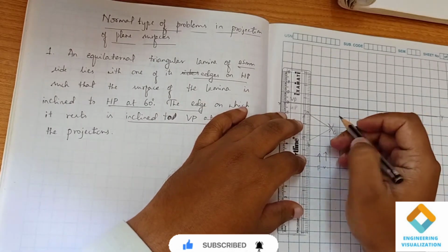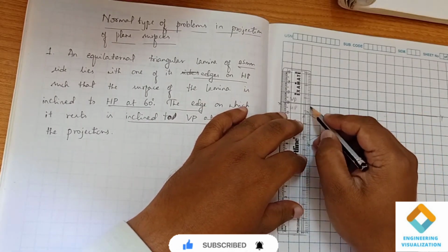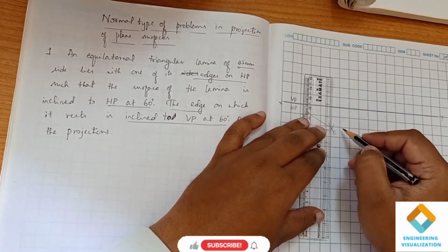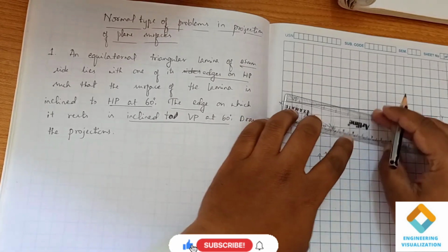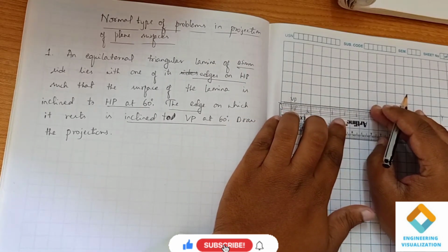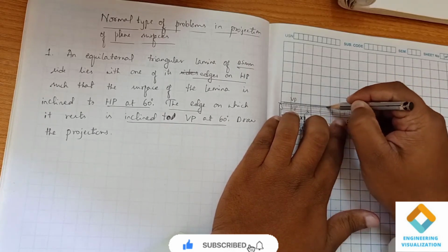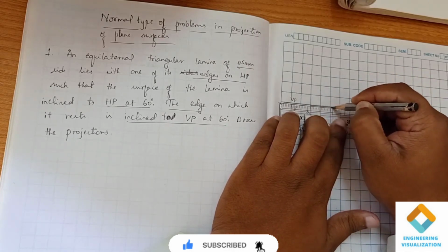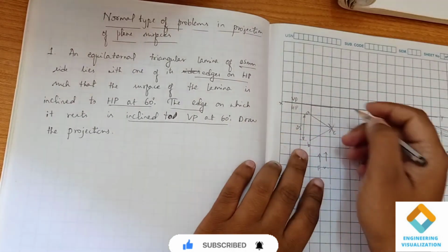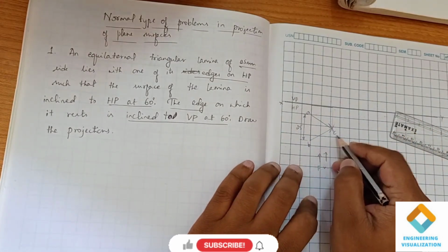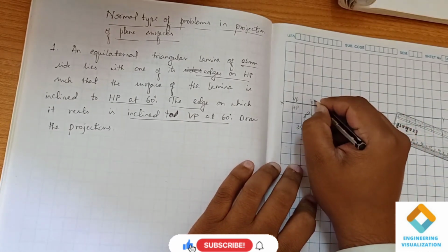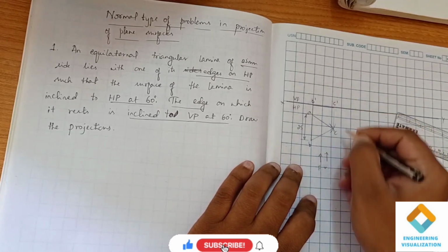With the help of the projection line, which will be a thin line here, we will get the view on the xy line. So remember it: the view which we get will be on the xy line. Now you see we are able to see the edge BC, so I will write B dash C dash, which is visible.